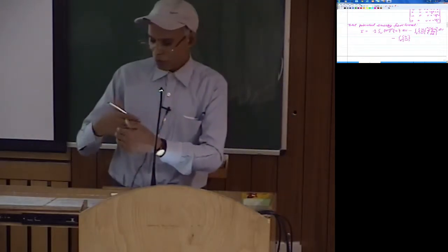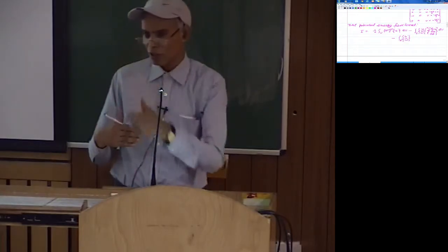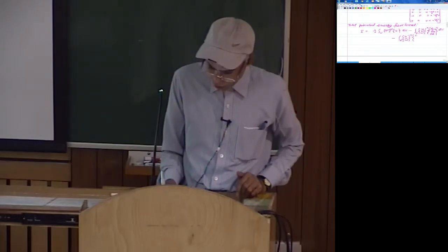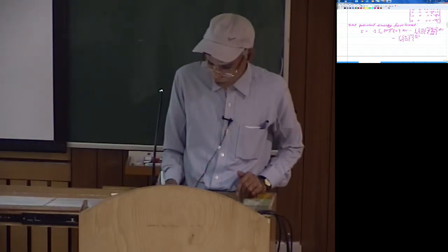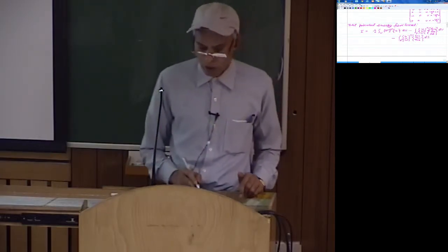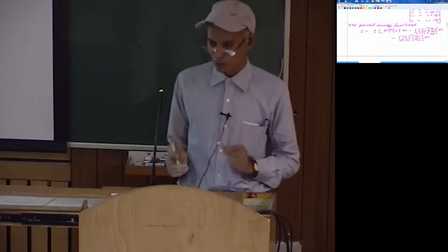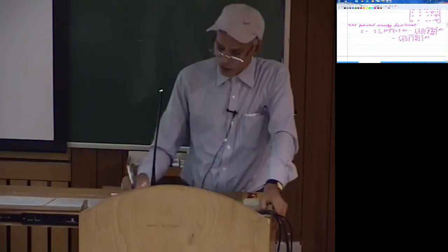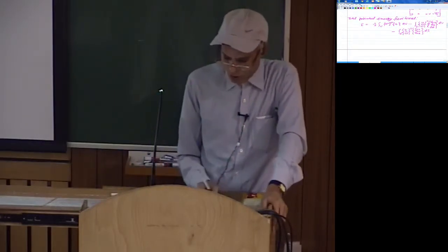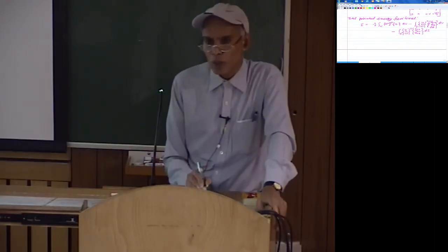On a surface you can have a traction component along x direction, along y direction, and along z direction. So the corresponding potential is going to be, let us say those tractions are Tx, Ty and Tz, and into dS. So this is now a surface integral, essentially integration over the outer surface of an element. Of course, in addition you can have some concentrated forces also. We are only including these, and you can always include the concentrated forces in this. So this is the form of your total potential energy functional.